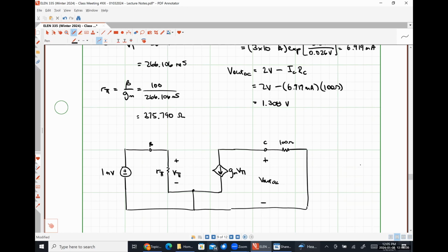So you're correct, Brody, but let's think about it kind of in a step-by-step thing because this is our first time really doing it, okay? So we have established, and I hope we're all on the same page, that the output voltage here is the voltage drop across the 100 ohm resistor. So I would argue that using good old Ohm's law, if we can figure out what current is flowing through the 100 ohm resistor, then we can figure out what our output voltage is.